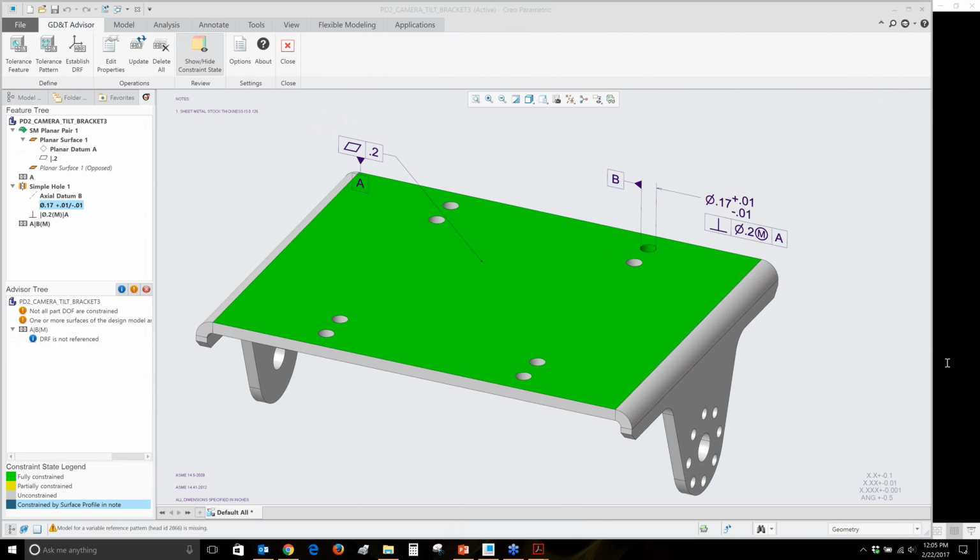So question here for how do we take the view states? So basically this is going to be using the same information as you are in the data set. So if you've been into an MBD class or you've gone through the process of using the annotations tab, you're still going to be able to use this in the view states that you would prior. So you could set up the MBD tabs across the bottom of your screen here for your view states, define those for the states that you would like to have, and then start representing those dimensions or the GTOLs in that view state that you want to have set for that.